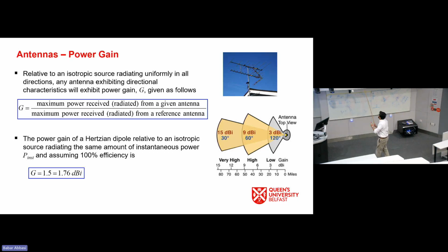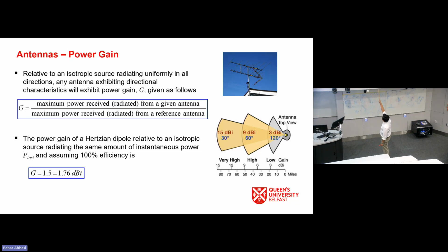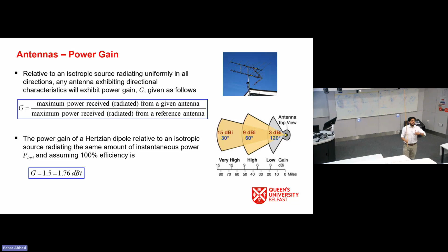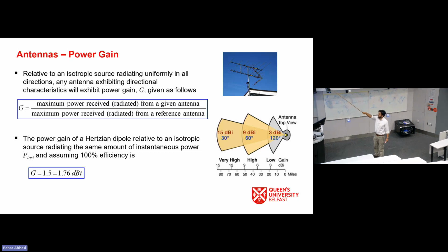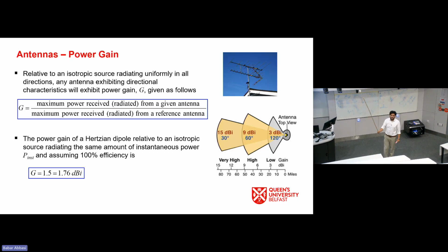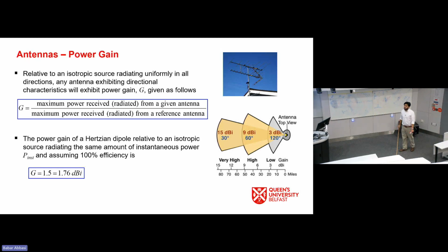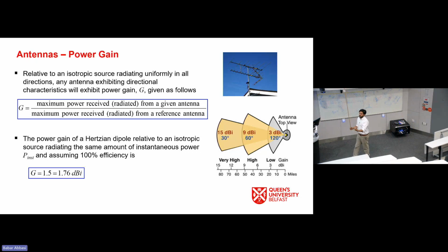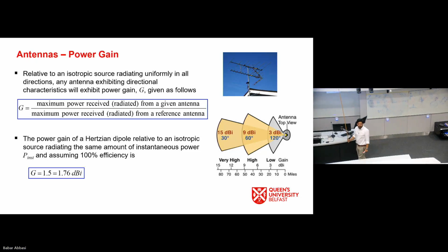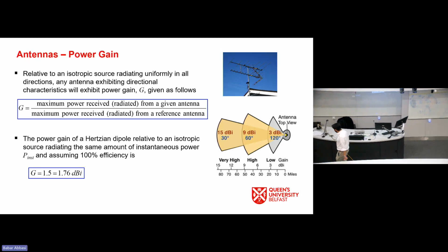So these antennas are for more directive purposes. A high gain antenna means it has more directivity towards one direction. So it will capture a signal from far away in that direction and can throw energy in that direction further away. Similarly, we have much more sophisticated antennas. For example, radio astronomy antennas have extreme gains, more than 50 dBi. And they have extreme capacity of receiving signal from far away distances. So that's why gain is an important term.